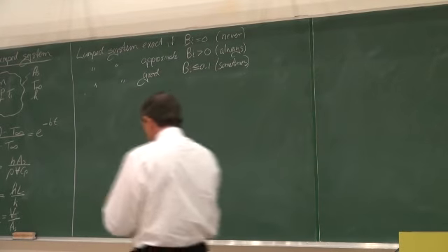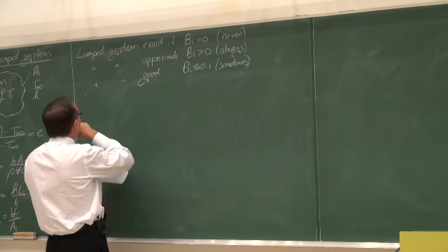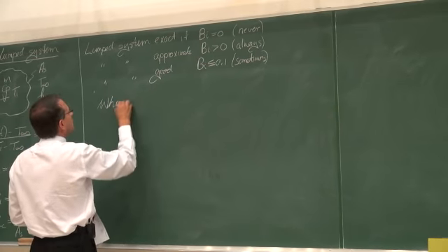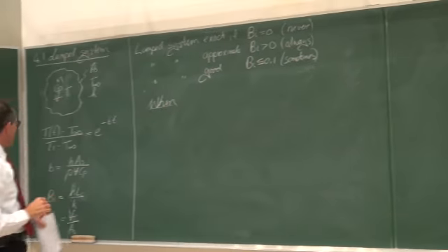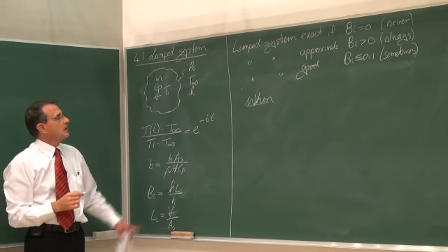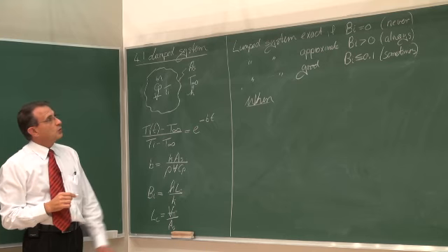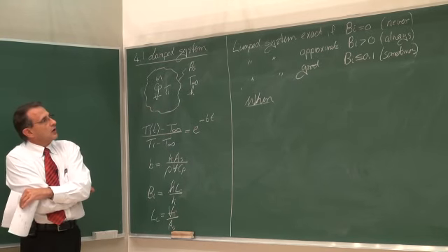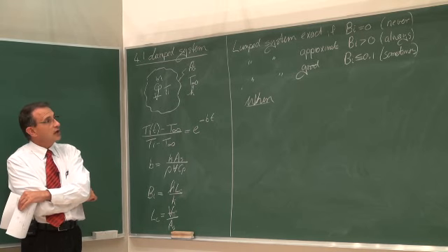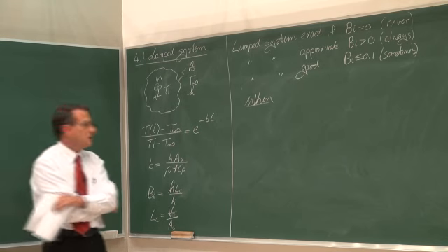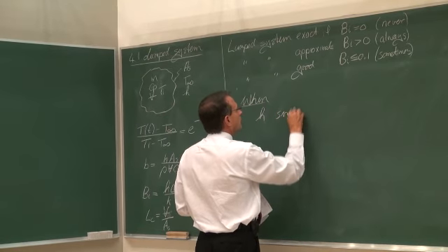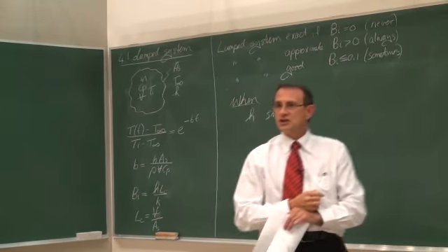If we look critically at the three variables that play a role, the Biot number would give us a small value, which means that we can use the lumped system approach when, firstly, the heat transfer coefficient is small.